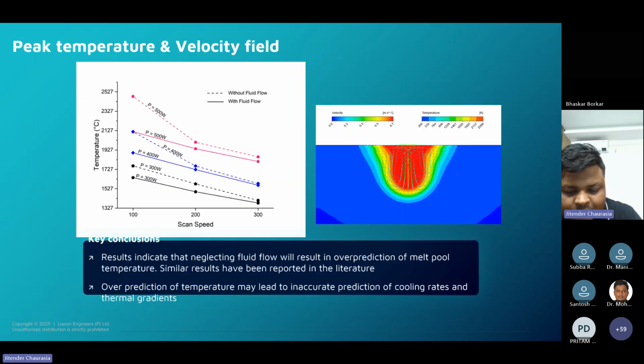So this was the whole intention of doing this, and also we try to understand how the fluid flow will happen, let me draw it here. For this material at this temperature, it will flow like this. So it will lead to deepening of the melt pool. In some processes, if your temperature is not exceeding, it even goes the other way. In that case, your melt pool will be wide, not much deeper. Again, it depends upon Marangoni flow and your material purity level also.